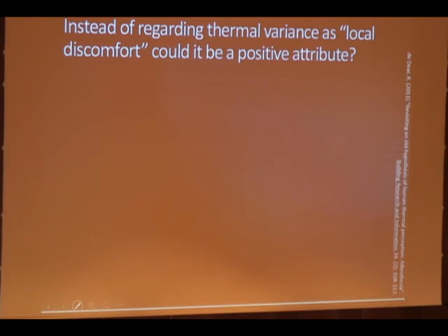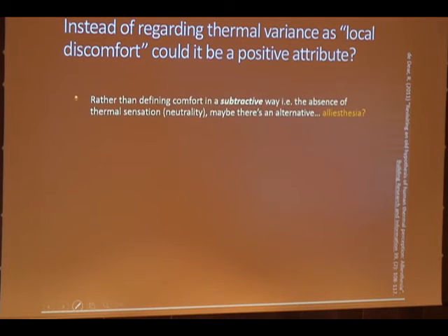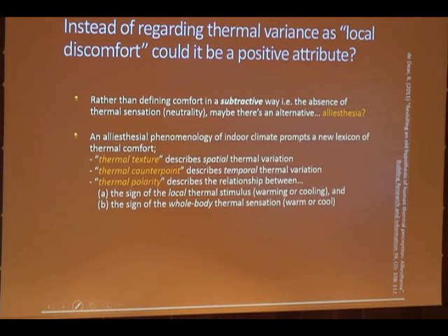So perhaps thermal variance and local discomfort could actually be a positive attribute in the thermal environment. And rather than defining comfort in a subtractive way, as the absence of thermal sensation, perhaps there is an alternative. And here we can refer to the alliesthesia concept, which I'll describe for you just briefly.